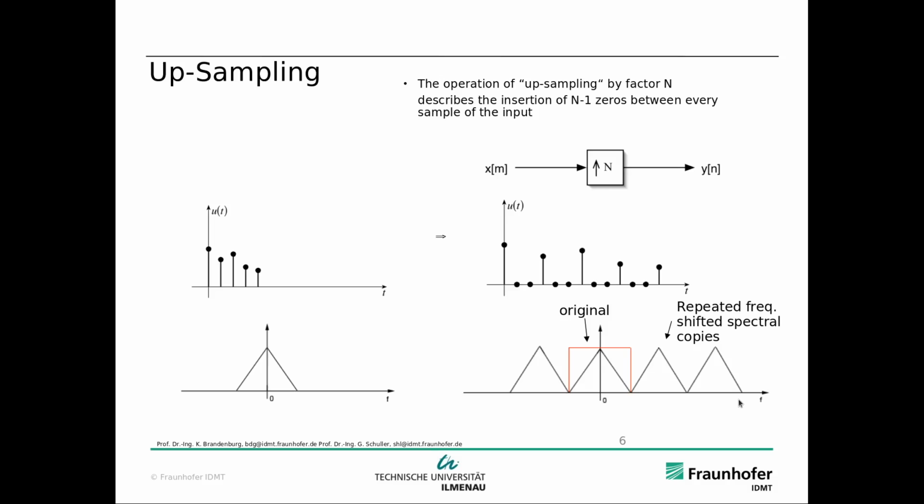So that's a property of upsampling, and that's why we need to have filters, right? For instance, if we have a low pass filter at the beginning, then after upsampling we need to apply a low pass filter which fishes out this correct spectral copy. Otherwise we have wrong spectral copies here. We can see with ideal filters that works. Here's such an ideal filter. This is the pass band with a factor of 1, so it leaves everything unchanged. And here we have the stop band, which has a factor of 0. That means it will zero out all the spectral copies which are at the wrong positions.